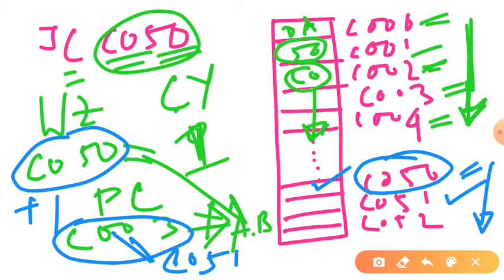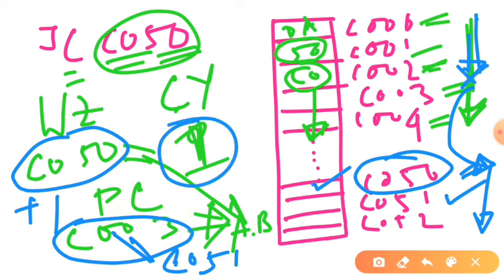As you can see, previously this was our sequence of program execution, and now we have a branch, or we have jumped to memory location C050 after C002 if the carry was 1. If carry was 0 previously, then this jump doesn't take place. Instead, we will follow the default way of program execution. After memory location C002 is read, the next instruction will be fetched from the next memory location C003 onwards.